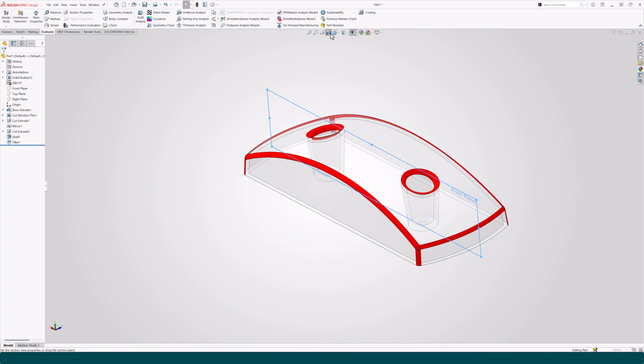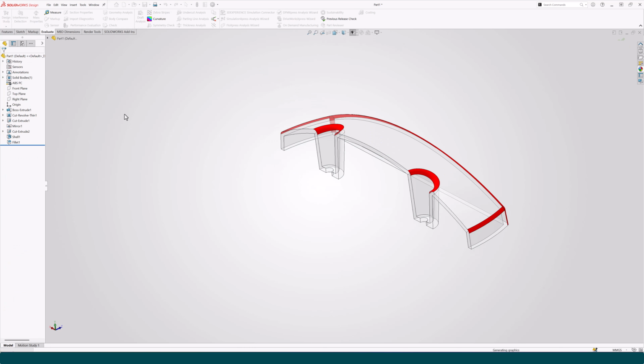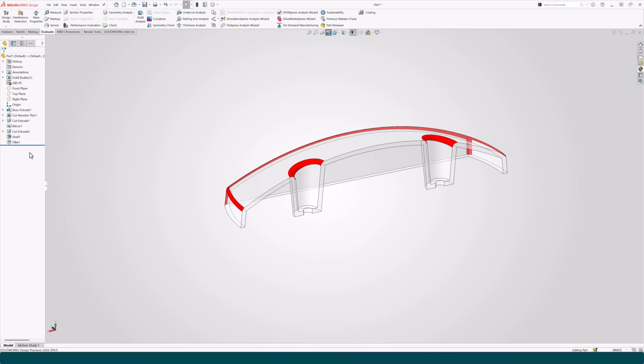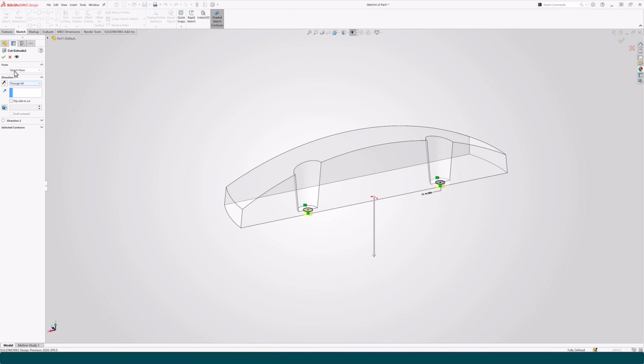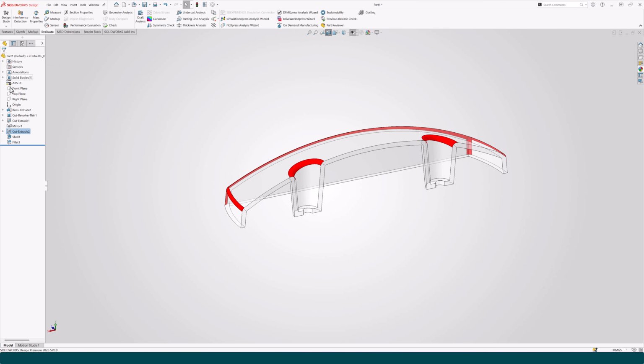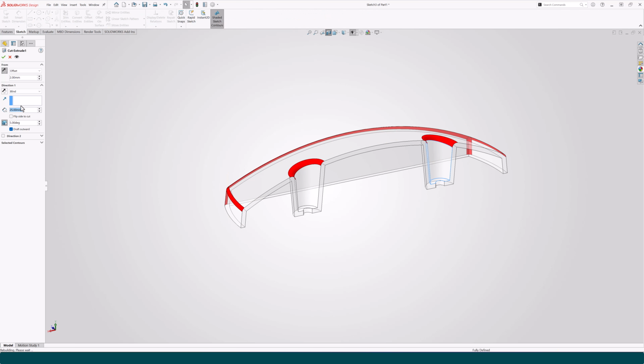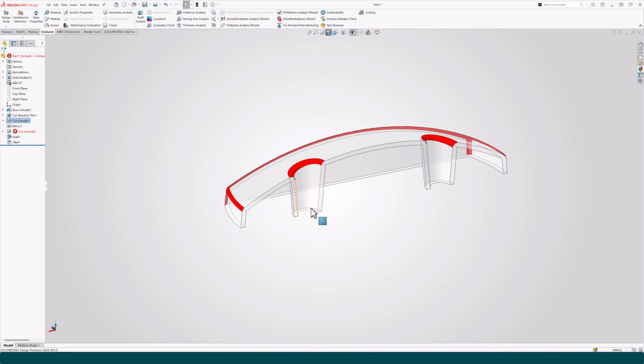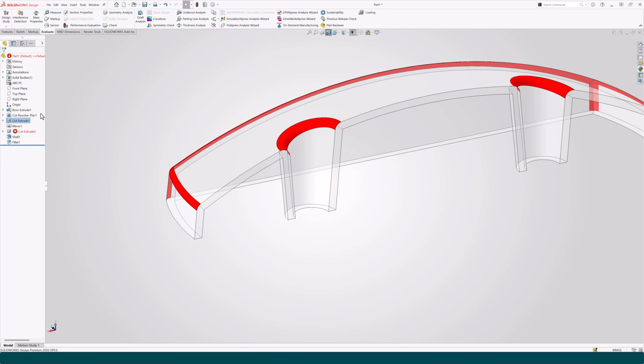And then I want to show you that offset. Let's cut a section through here, and looking at the cut extrude command, not this one. Let's get out of here. And let's go back to the original one here. If I change that from being sketch plane, it goes directly from where I sketched it. And that's not what I needed. I needed that wall thickness of 2. So the trick here is to use that offset command.